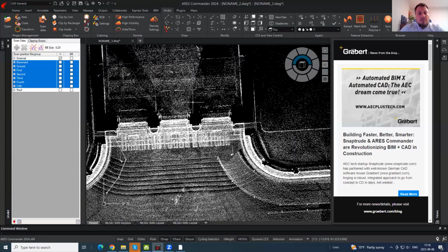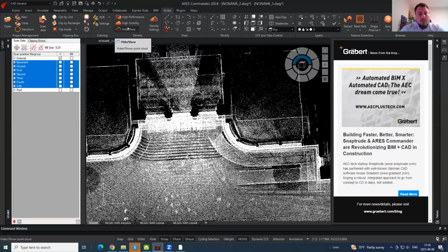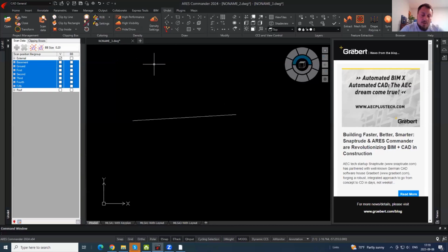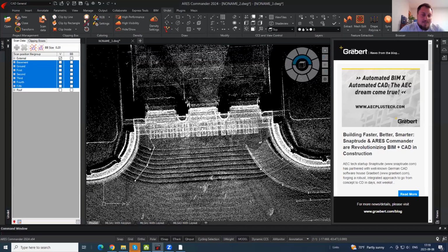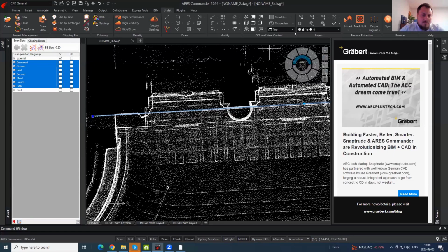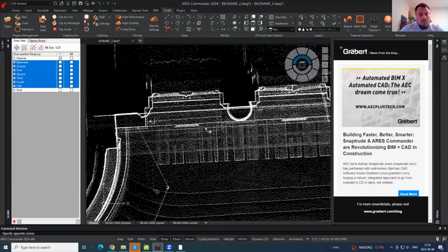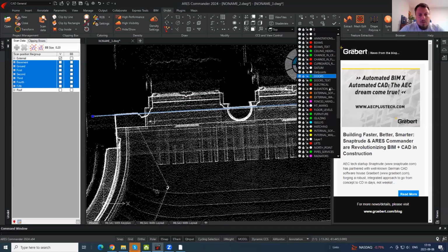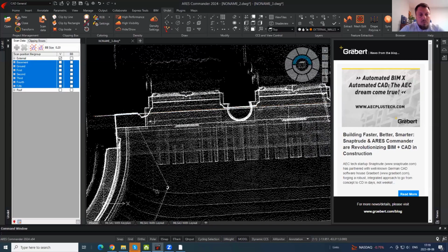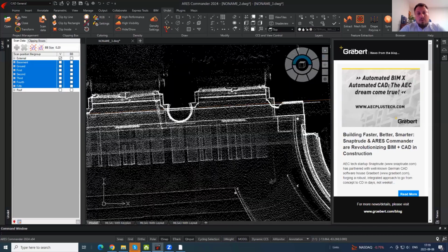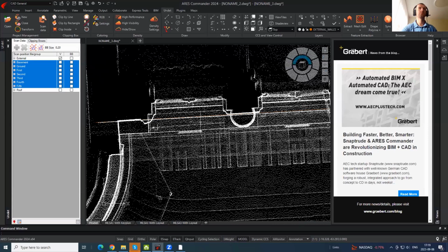One thing: you just activated the snapping to point cloud points, and when I'm talking to customers, we always ask if it's better to snap to a point cloud or not. For example, you're doing a lot of point cloud to CAD projects, and you're snapping to a point cloud or not? Only when you use special blocks to snap.